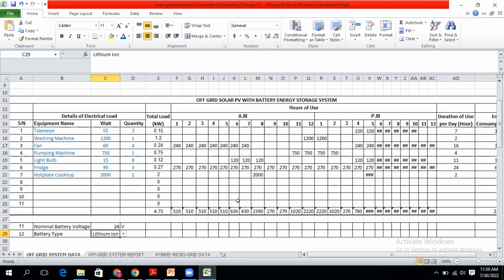Then for batteries, I will always recommend, it depends on the cost anyway. Sometimes it depends on what your clients can afford, right? So there are high quality lithium iron phosphate batteries. I will recommend lithium iron phosphate. There are different technologies, different chemistry. Those ones are too costly now. Exactly. Like I said, if you can afford it, I would recommend lithium.